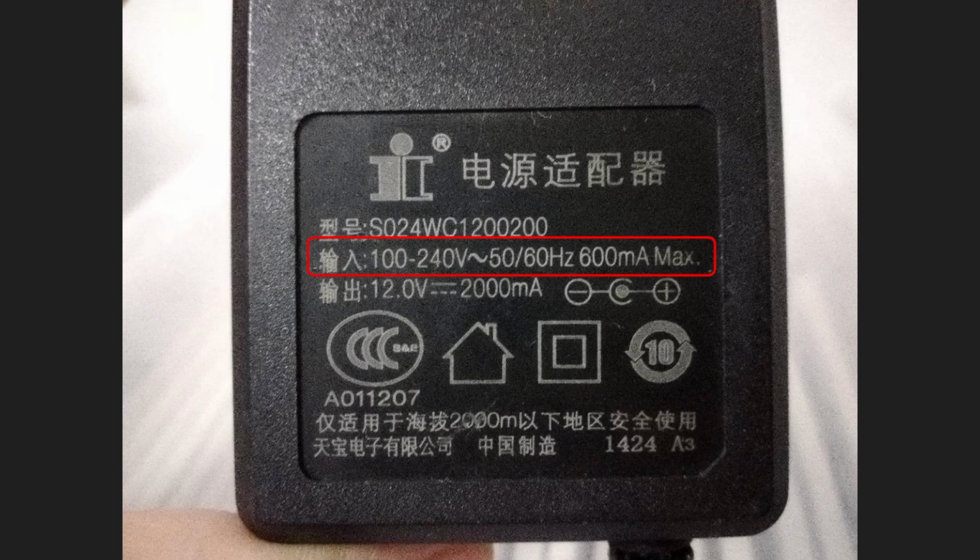Like in our device list in our radio room, we have a power supply which operates only in DC. It's not a transformer, it's a rectifier, which converts from AC to DC. The rectifier works with 110 volts, so if we accidentally connect it to our main circuit, it will burn out. So make sure that if you bring your chargers to other countries, it is 100 to 240 volts, and 50 or 60 hertz.